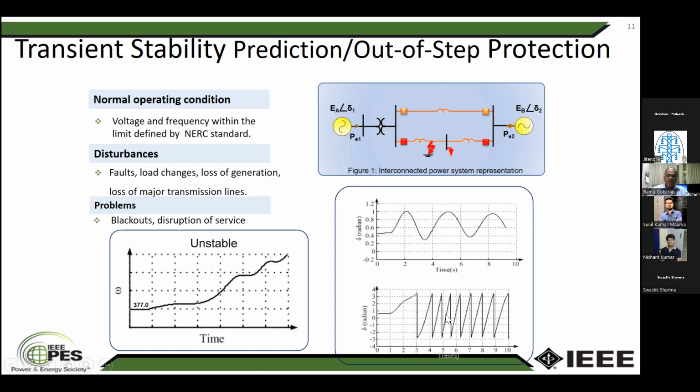The way it works in the North American region is that if we have one pole slip, then we trip the generators. Obviously, at the instant when the pole slip happens, we cannot trip the breaker because a very large restriking voltage would be generated. So we wait for a favorable angle. Typically, after a pole slip, we wait for 270 to 360 degrees, which is around 0 to 90 degrees, plus or minus.